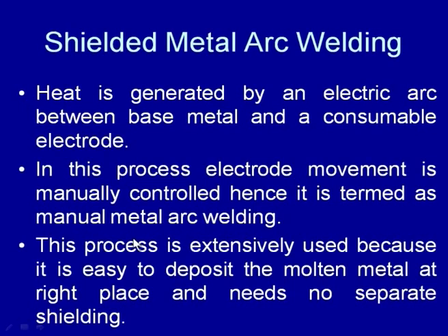So, this process is extensively used because it is easy to deposit the molten metal at the right place, and it needs no separate shielding. Whatever shielding is required to protect the weld pool from atmospheric contamination is obtained by the thermal decomposition of the flux material, which is there in the form of the coating on the electrode.